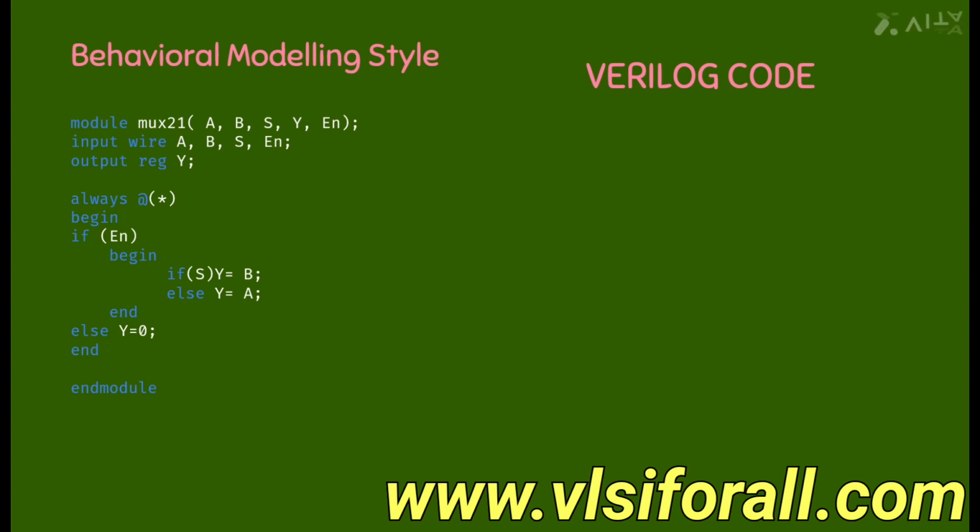After we do this, we declare the inputs and the output explicitly differently, with the input being called wire and the output as reg. We put in all the inputs and the outputs, definitely with the enable signal here, so that we can also understand the importance of enable in a circuit.